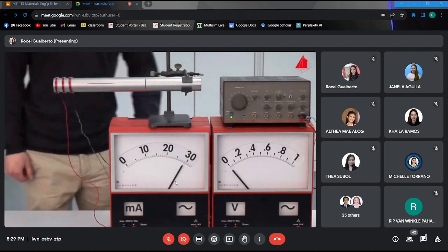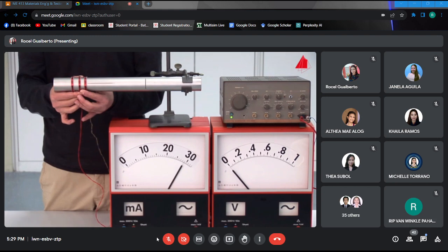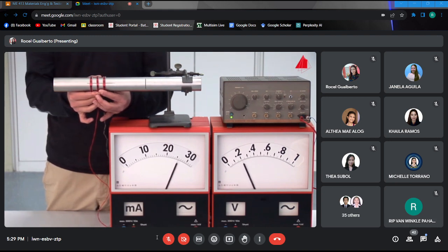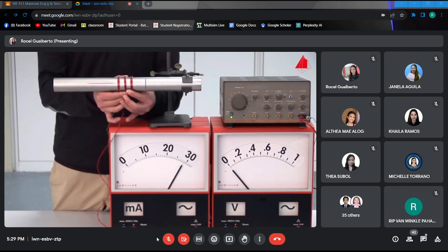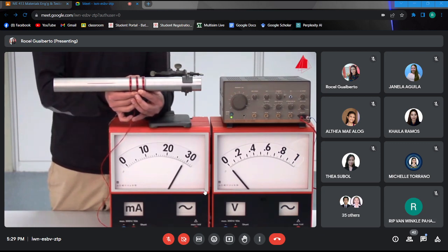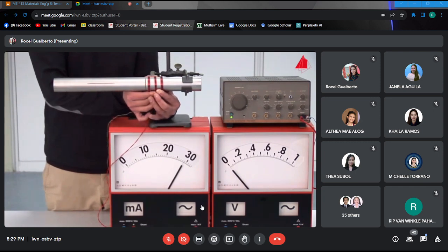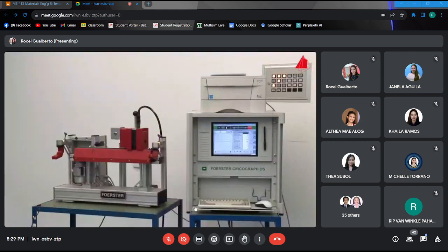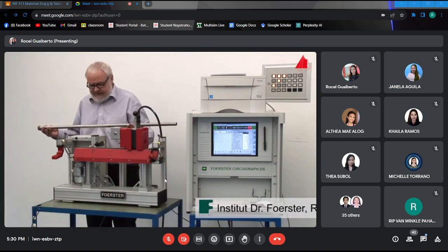We have set up this test arrangement in the laboratory too. The voltage meter clearly indicates the ends of the longitudinal saw cut. Unfortunately, even this arrangement cannot detect the saw cut in circumferential direction. If the coils are optimized even further, much smaller defects than our large saw cuts can be detected.